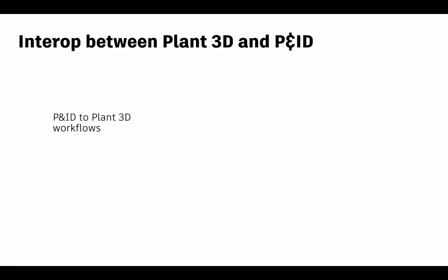So traditionally, if you work in a P&ID or a Plant 3D project, you need to have P&ID drawings corresponding to the related 3D modeling part of it. This involves you working from a P&ID line lists window that displays all the line elements and the segments and basically the associated fittings, the valves, and the inline components in a drawing.